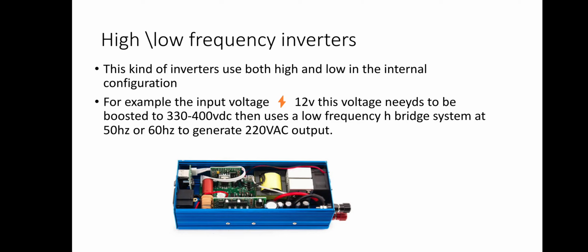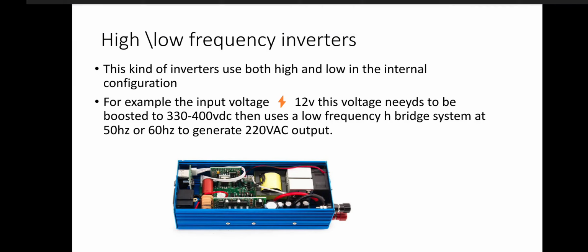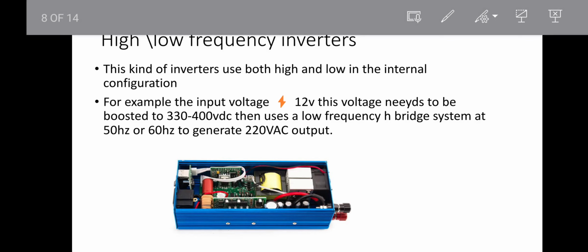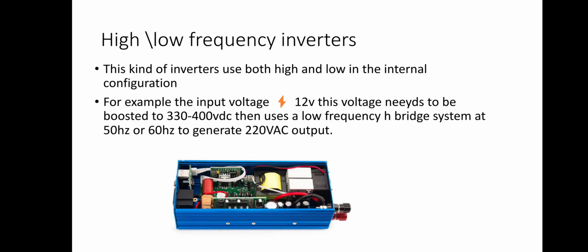Such kinds of inverters are easily damaged due to the kind of circuitry they use. This one uses a MOSFET for its output, while the transformer based systems use a transformer for output, but the transformerless uses MOSFETs for their output. So that is one of the differences, and that is one of the side effects. When there is a problem, the MOSFET will directly just burn. But when it is transformer based, most times it will equally affect the MOSFET too and bypass the transformer.